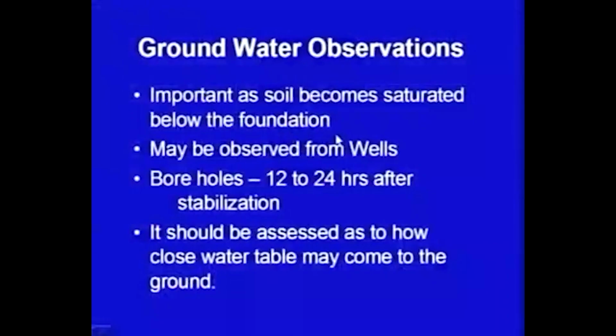The groundwater observations are also very important for foundation engineering problems. When the water table is high, the subsoil strata becomes saturated and it may enhance the settlements. Secondly, it may also reduce the shear strength. So, one of the objectives of the soil exploration program is that we should know how much water table depth is there.